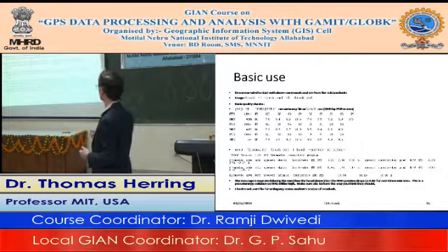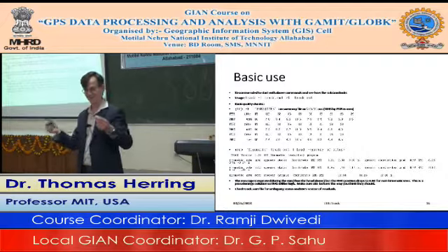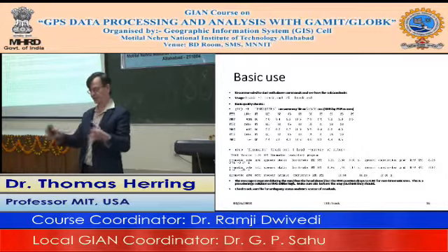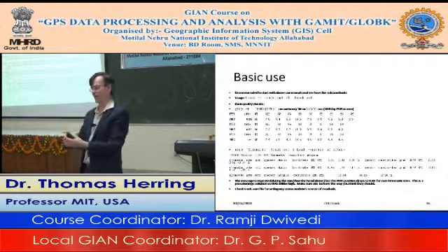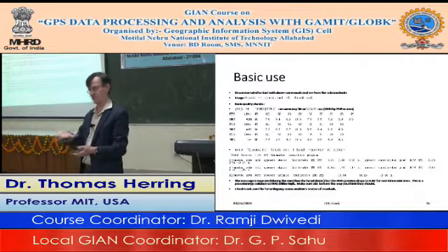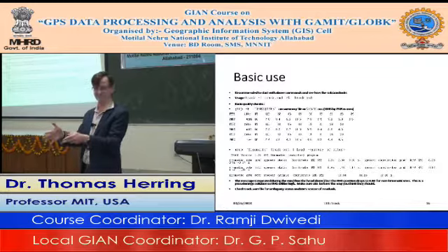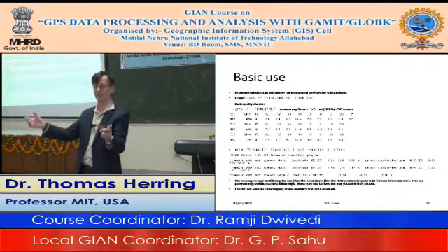When we do really long baselines for earthquake cases, the sites are static at the beginning, and we typically know their coordinates very well. They will have a period of seismic wave arrivals, and in many cases after that they're static again. We can tell track that there's a dynamic period in which there is kinematic motion of the stations, but it's static before and after.